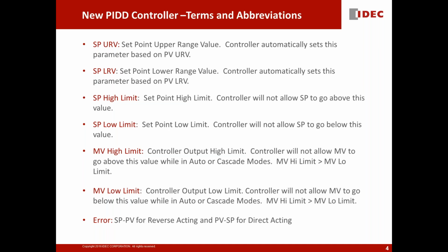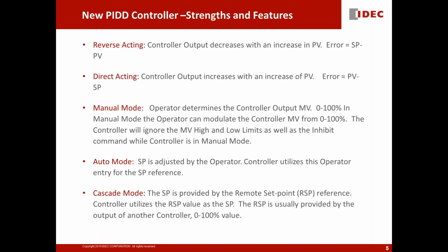And hopefully everybody who had any experience with PID realizes that the error is nothing but the difference between the set point and the process variable, in both direct acting and reverse acting, or regular acting.